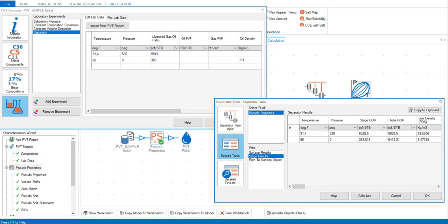All right, in summary, the current equation of state model currently provides an adequate description of some of the fluid's properties. In this case, the liquid density and the GOR from the separator experiment, and also maybe the Z factor from the CCE, while the liquid dropouts are not very well matched up to now. And now we can take a moment to consider these results, and we can also consider the steps to develop a possible regression strategy.